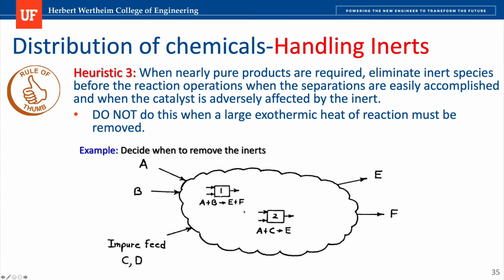Something that we forget is that even though in the simulation we add pure ethylene, for example, we may need to check our sellers because ethylene may not come pure, right? It may come with a percentage of another contaminant because the purity of the ethylene or the raw material directly affects the price of purchasing that particular chemical. So sometimes we sacrifice low purity and then remove that before sending it into the reactor if needed.